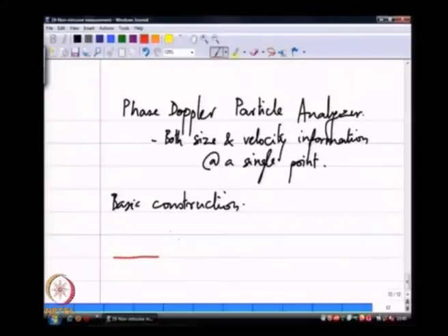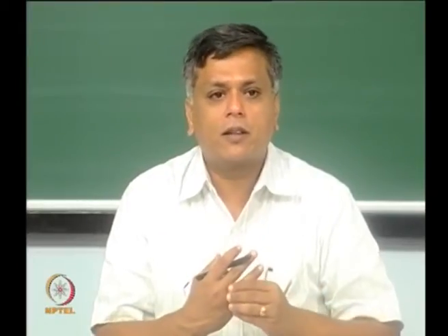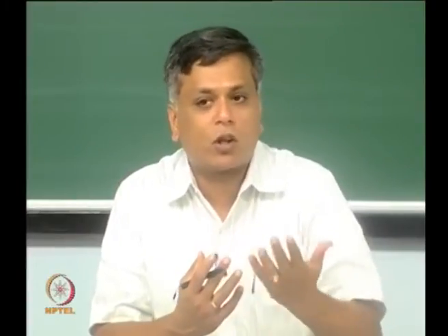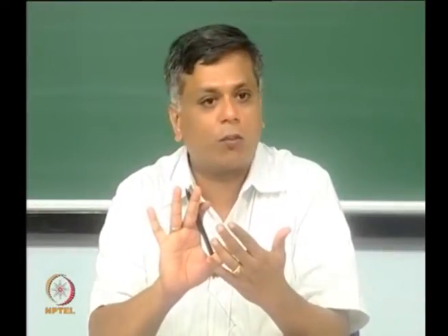Take a light beam, a laser. You do require a laser here. For PIV, really you do not require a laser. There have been some studies where people have used reasonably high intensity LED sources to get PIV, because all I am doing is imaging. I am getting two snapshots of a moving set of particles, and I am not taking advantage of coherence in the light source in a typical PIV system.